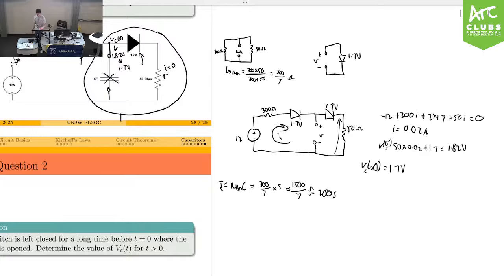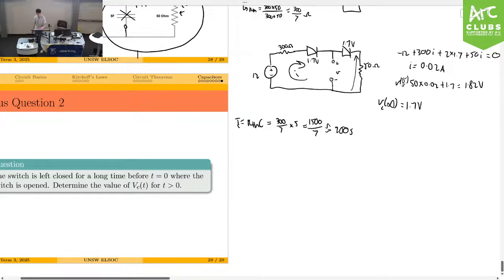If I was your lecturer, I would include a question like this. But yeah, this diode pretty much clamps the voltage at 1.7 volts instead of letting it decay to 0. Now, in reality, it will go down to 0, because if you leave a capacitor on your table, eventually it will go down to 0 because there's resistance in the air, and so it can lose energy that way or through some other non-ideality. But ideally, it goes to 1.7.